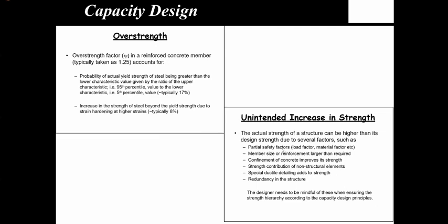And sometimes we provide more reinforcement than what is required, and also confinement increases the strength of the members, and strength contribution from non-structural elements, and special ductile detailing adds to the strength and redundancy of the structure as well. We don't really address these directly, but these all add to the strength of your overall structure, right?